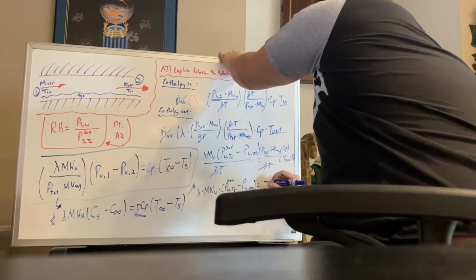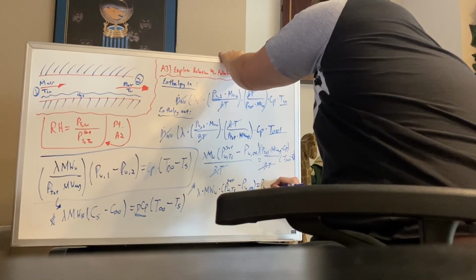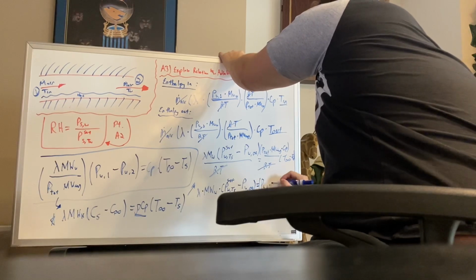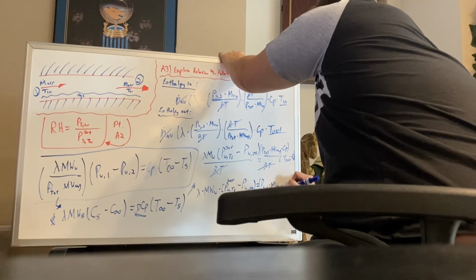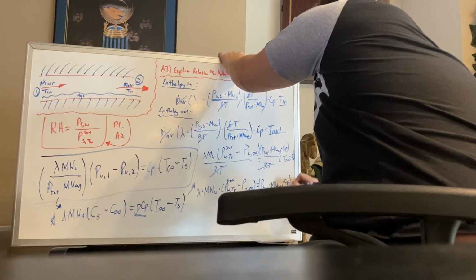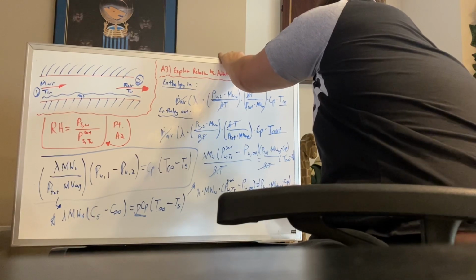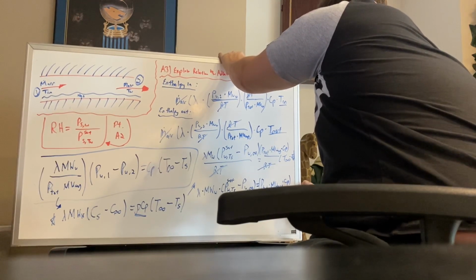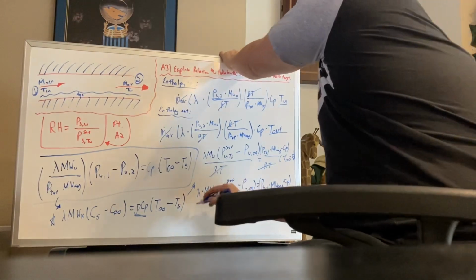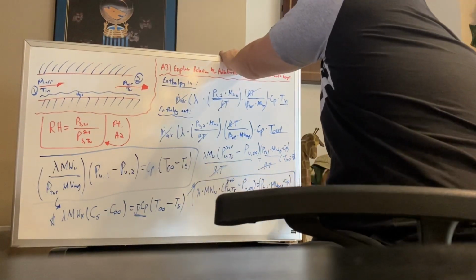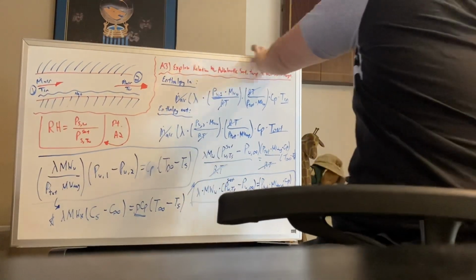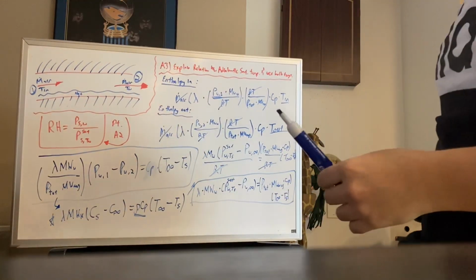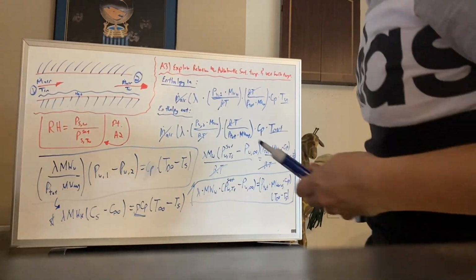It's all equal to the total pressure multiplied by the average molecular weight multiplied by the specific heat capacity, multiplied by the temperature difference between some point far away and on the surface. So this is actually our relation between the adiabatic saturation temperature and the wet bulb temperature.